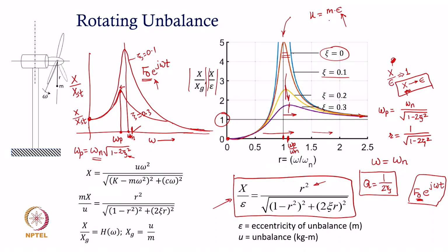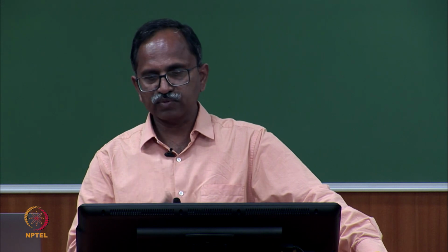And so, the physical balancing method will eventually try to minimize epsilon to a very, very small value, which leads to a reduced amplitude of vibration, which is expected here. So, practically you can expect that reducing unbalanced eccentricity reduces the response.